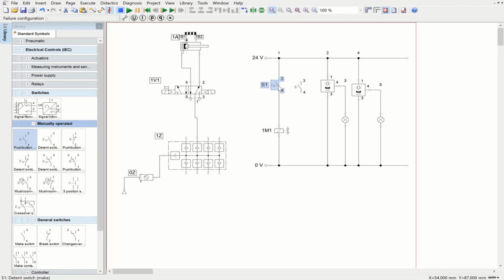And I have to change this one. We can use the detent one, but we have to be very careful about the case of signal overlapping. I will have a video on signal overlapping on magnetic proximity sensors in electropneumatic circuits, and we will see how we can avoid these conditions inside electropneumatic circuits too.